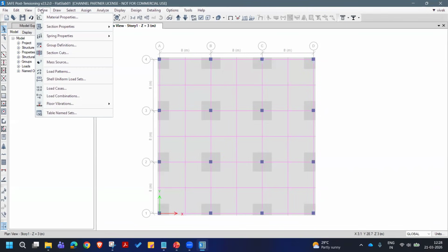and then modifies the flexural stiffness modifiers, and the displacements are computed in iteration until the maximum displacements are not varying much, or the number of iterations specified is not exceeded. So typically this is a nonlinear behavior. So the nonlinear analysis will be utilized for this. So that is a background of it.